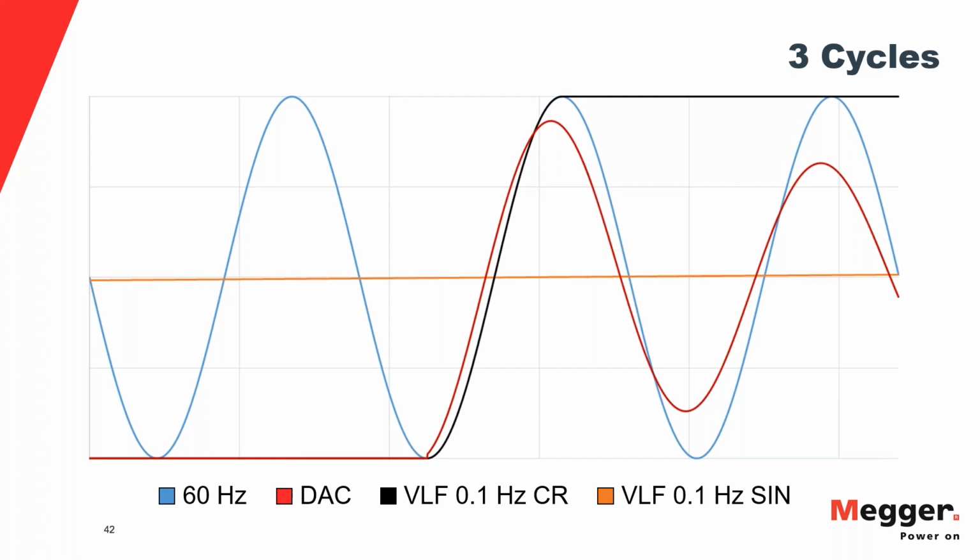But then I told you about the faults that are very sensitive to the rate of change of voltage, to the gradient in the accessories, in the layered interfaces. And you can see now why all practical testing pretty much shows that sinusoidal is not up to the challenge. If you want to do proper PD testing and get power frequency comparable results, you need to use a voltage that actually has been proven to be comparable to power frequency. So sinusoidal is not recommended for these things.